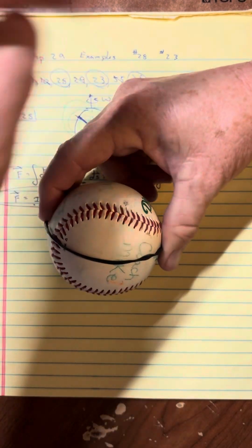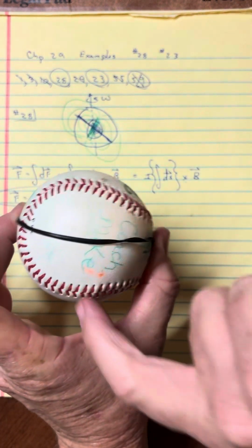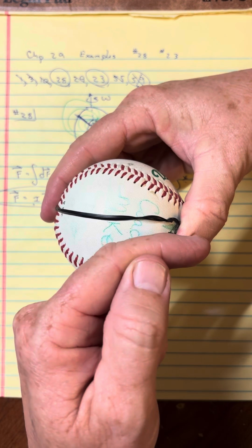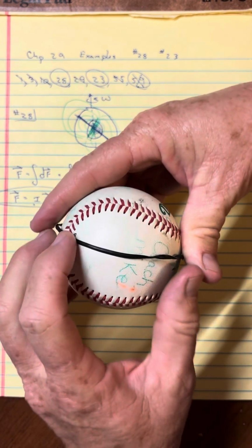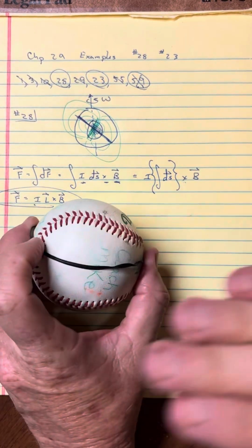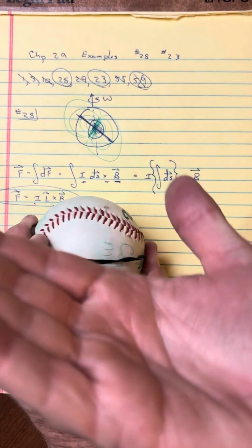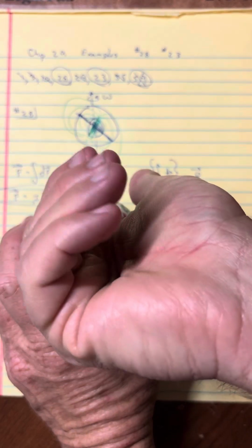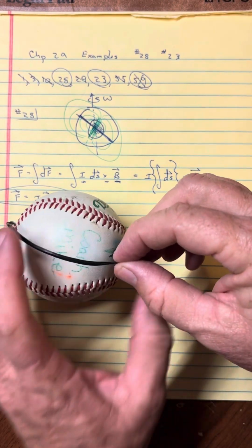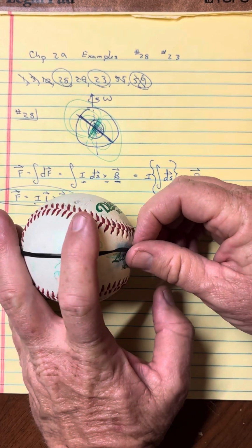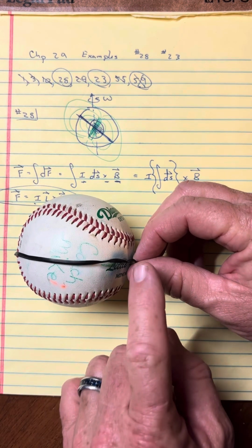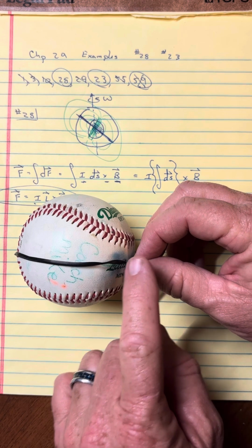And if I call the top of the screen the north and the bottom of the screen the south, then if the current goes east to west, and I do this cross product, I'd put my fingers in the direction of the current, rotate my hand so that I can close towards the magnetic field. And notice my thumb is down, so that would make the wire get pushed into the earth magnetically. Exactly the opposite of what we want. So that's not good. So we don't want the current going from the east to the west.